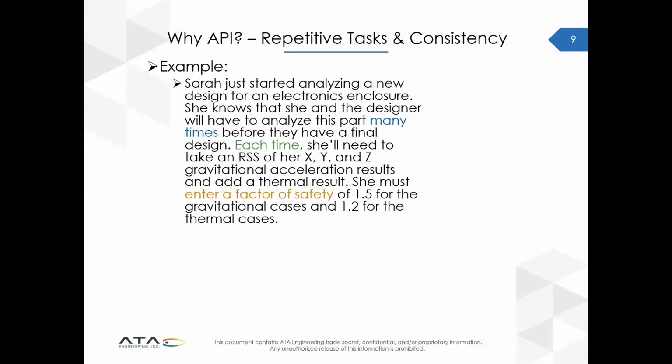So let's say we've got our analyst, Sarah, and Sarah just started analyzing a new design for an electronics enclosure. And as with any brand new design, she knows that she's going to be working with the designer, going back and forth, changing thicknesses, moving gussets, going through all of that. And she's going to have to analyze this part a lot of times. And every time she needs to get that same results combination, which is an RSS of some gravity results, an X, Y, and Z, with a factor of safety of 1.5, and a thermal result with a factor of safety of 1.2. So something that we see a lot as analysts. So let's look at this a little closer.